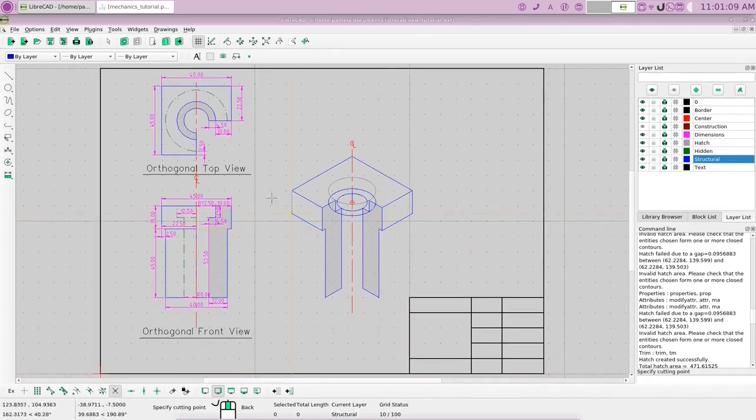Well, if we snap on an end point, okay, we could snap right there and cut that there. Now let's choose it again and snap on end point there. Okay, now let's right click to get rid of that. Let's highlight that piece that we took out, hit your delete key, and it's gone.